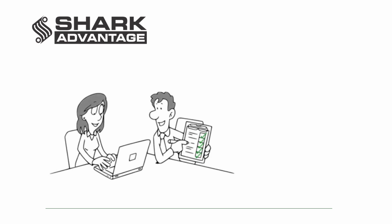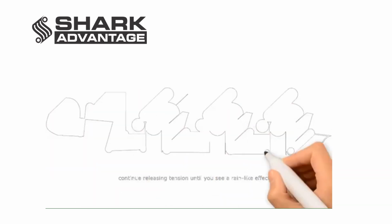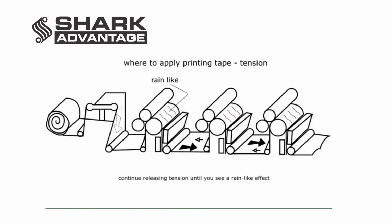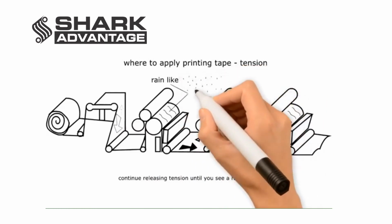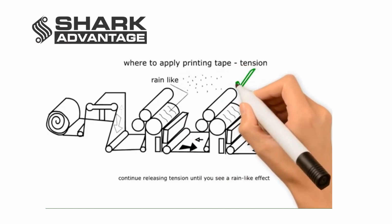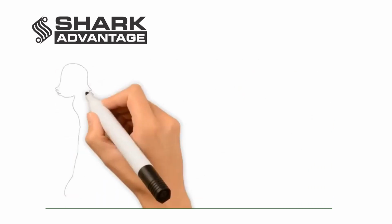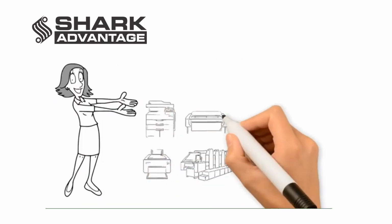Did you know that we can adjust machines for the highest performance results? How do we do that? When Shark Advantage sheets are installed on the machine, tension has to be released slowly in a step-by-step process. Once you see a spotted look on the material surface, that means your tension is correct and you can start printing and converting. Woohoo! By the way, web converting machines also follow the same procedures as printing presses.